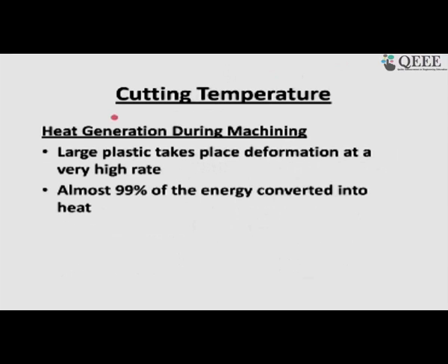So, friend, first of all it is heat generation during machining. Now, machining is definitely a deformation process. We do lot of experiment by deforming material in material testing laboratory, but this is a deformation whose magnitude and rate are unmatched by any other processes mostly. So, these two things, large magnitude of deformation and a very high rate of deformation, that leads to very large generation of heat, and which will lead to rise of temperature. Now, effect of this consequence.